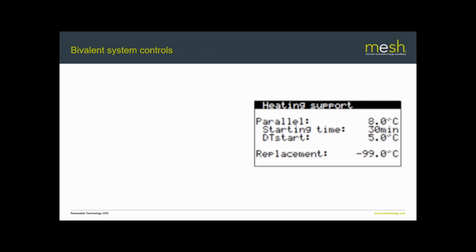So let's talk a little bit about system controls. In most systems, you will get some sort of demand signal coming from the heating, but that goes back to the heat pump manager. So the heat pump manager acts as the master controller in the system. Now this whole section is quite generic because the way that different heat pump manufacturers and different heat pump controllers work does vary. But as a general rule of thumb, this is a pretty good place to start. So the heat pump manager acts as the master controller for the system.